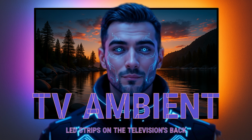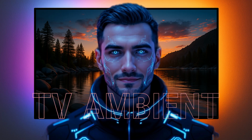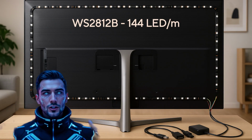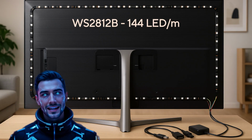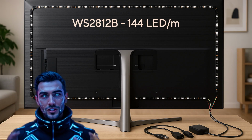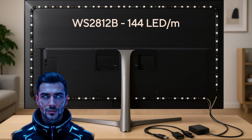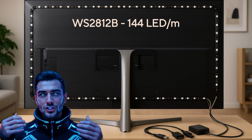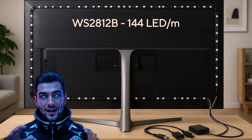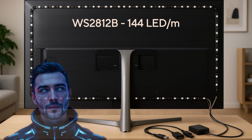Now that we have all the components, it's time to install the LED strips on the back of the television. I recommend using addressable RGB LED strips, such as the WS2812B or similar models, with a density of 144 LEDs per meter. They're perfect for achieving a smooth and precise Ambilight effect, just like in professional systems.